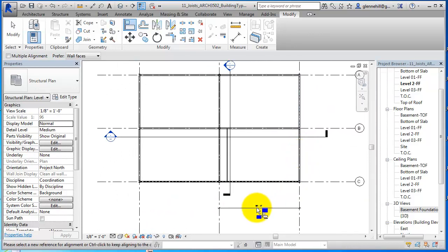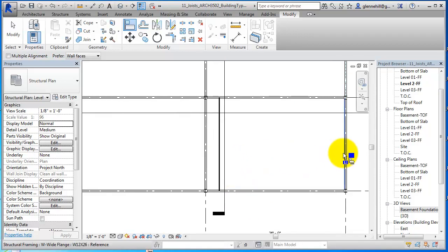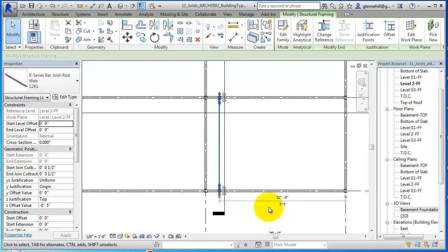So that's 36. If we divide 4 into 36, that's 8. So we're around 8. And we could lay these out at 4 foot on center and go forth if we wanted to do that. Once again, this is set out at 32.6 right now, so it definitely should be an increment of 4 feet, which would be 32 feet, right?